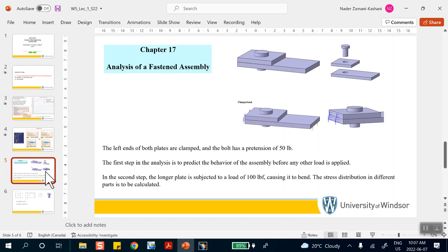Now, first of all, you don't model the bolt unless your job is to design the bolt itself, for example. Look, here's a multimeter, and there are some screws here, 1, 2, 3, 4, 5, and maybe I want to throw this thing and find out what the stresses are, because that depends on whether it's going to break or not. Of course, you can't do something like that with CATIA. You have to use some other explicit solver to do that. If you're just dropping it, you don't know what the forces are, etc.